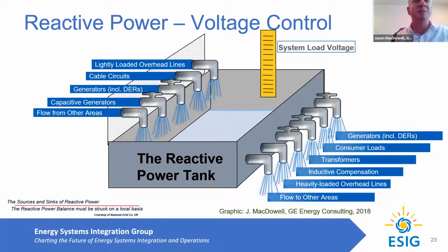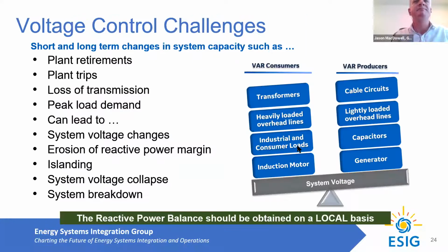Nick will talk about stability, transient stability, and weak systems. But remember this relationship: the more reactive power you have into the grid, voltage goes up, and then the more coming out of the grid relative to the balance, the voltage goes down, okay?